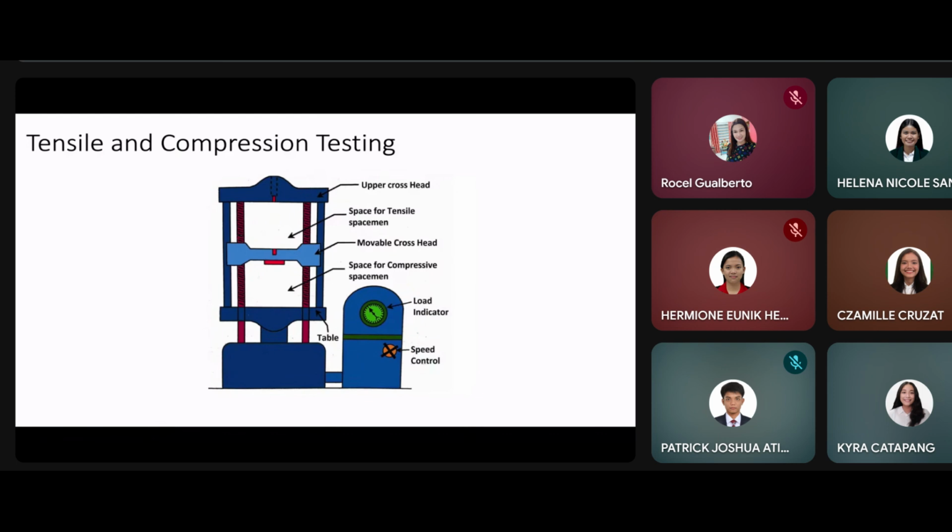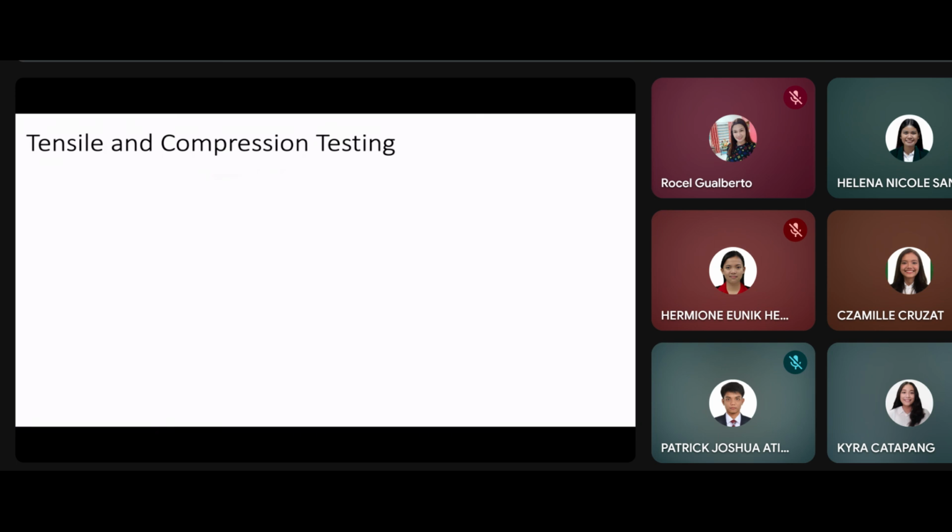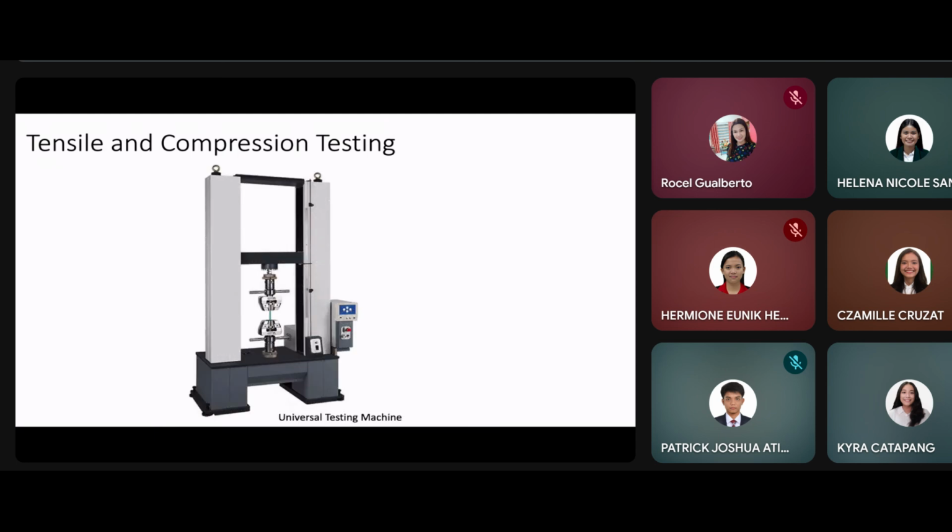Tensile and compression tests are the most commonly used destructive testing methods in industry. The evaluation of mechanical behavior of a sample under conditions of tension and compression can be performed to provide basic material property data that is critical for component design and service performance assessment. Testing can be performed on a mechanical material sample or on full-sized or scaled models of actual components. These tests are typically performed using a universal mechanical testing instrument.